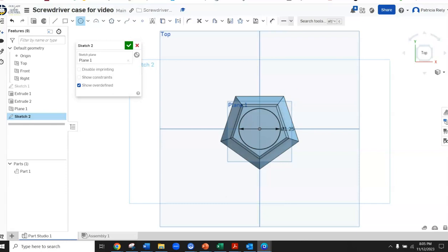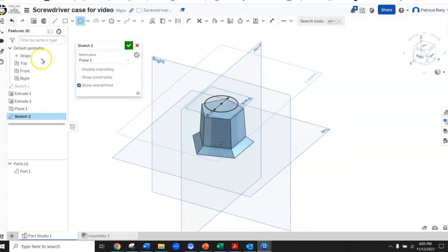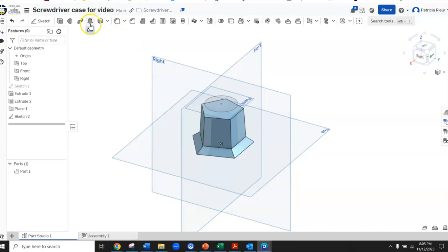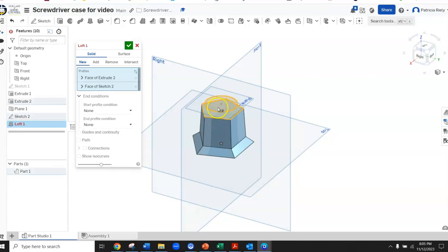So now we're going to try the lofted. So again, I'm going to kind of come this way so I can do that. So what are we going to loft? It says create a circle on the top and then loft the pentagon. Okay, so I'm going to loft. So I need the loft command. So I believe I can accept the circle. This is your loft command. So you're going to loft from the pentagon, so light up your pentagon, to your circle. And that's exactly what I want. That's the loft. Now, do they have any requirements? Yes, they do. Well, actually, no, it's just lofted, and mine's lofted, and that's beautiful.